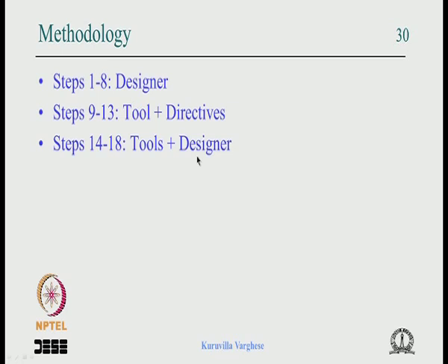So I have taken you through a whole case study, starting with a specification. We have seen how to offload the processor by designing a data acquisition system. Basically we described the system and came up with the block diagram: the ADC, the host, the controller, and the temporary storage, for which we chose a FIFO. Then we interconnected them, put in the timing diagram, identified the subsystems, updated the timing diagram, derived a control algorithm, drew the state diagram, and developed the next state table and the output table.